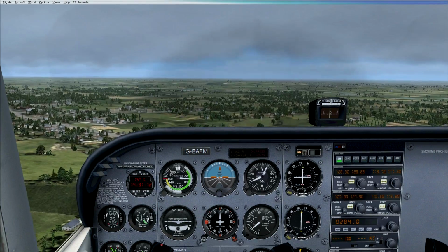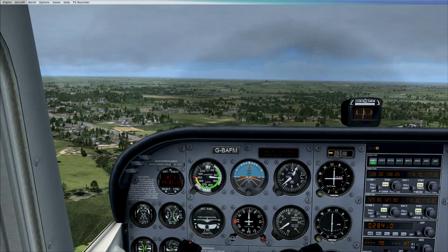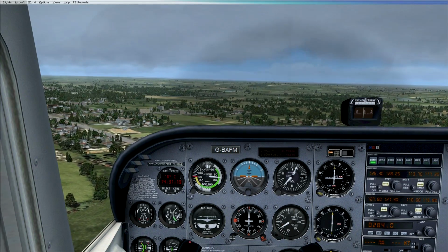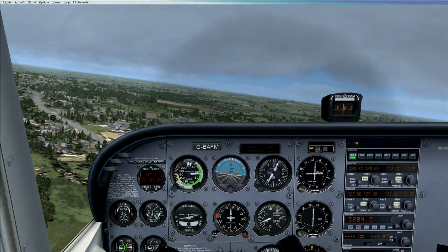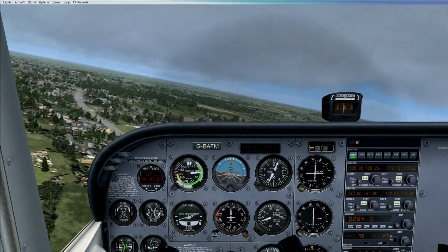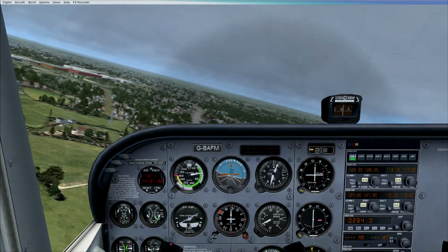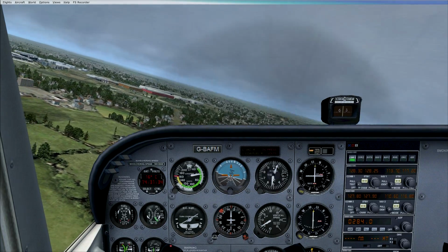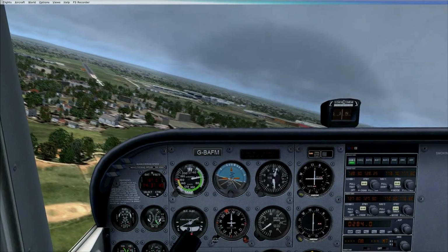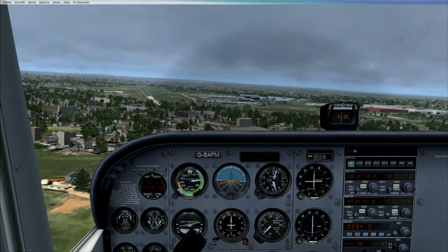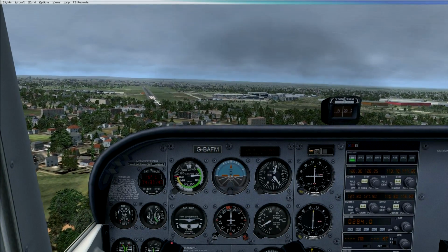Now I'm looking to turn onto our final course at about 600, maybe 500 feet. The airspeed's at 70 knots at the moment, so I'm quite happy with that. And we're going to turn now. Speed's coming back gradually, just need to watch that in the turn. Same thing as when we were doing our climbing turn. We don't really want to turn too steeply at low airspeed, so we're just dropping down towards 60 knots, rolling out a little bit there because we're slightly early onto our turn to finals there.